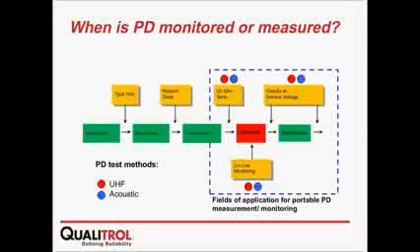Generally speaking, for medium voltage to high voltage equipment up to 220 kV, people choose an acoustic-based measurement. For extra high voltage, usually the OEM supplies the UHF sensors built in due to the customer specification, and using those sensors, customers and OEMs do the on-site test during commissioning using the UHF method.